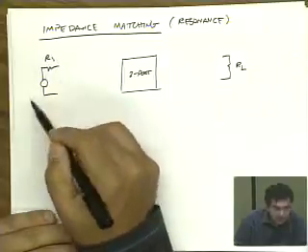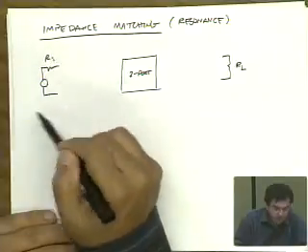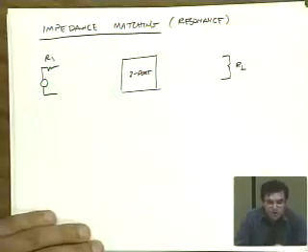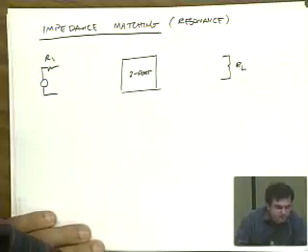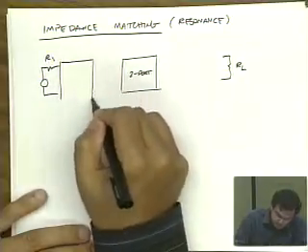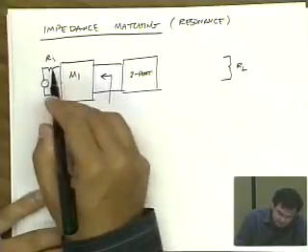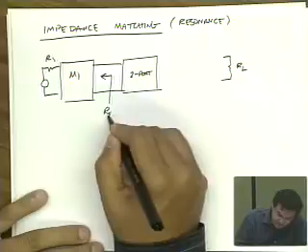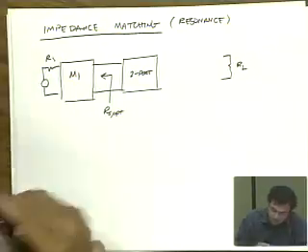For instance, this might be an antenna, and the person who designed the antenna says, well, when I design my antenna, the best I get is 300 ohms. So your source impedance has to be 300 ohms. And you say, well, actually, I want 10 ohms. I kind of want to be driven by 10 ohms because that gives me better power gain. And the antenna designer says, tough. So what do you do? You actually design a matching network. So we'll call this M1 that transforms RS into, let's say, RS opt. Or more generally, transforms ZS into ZS opt.